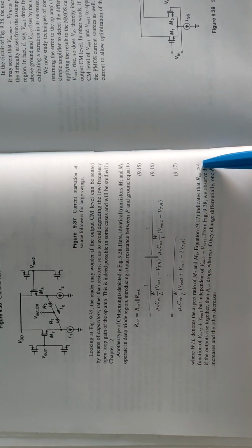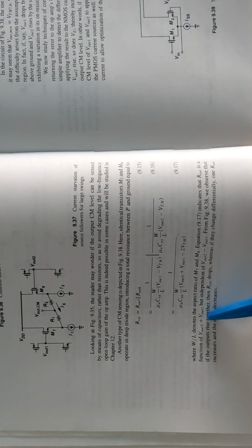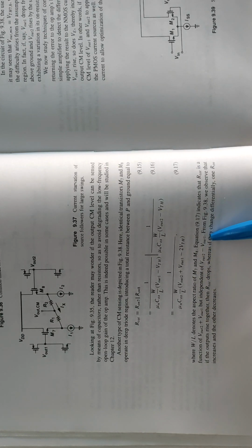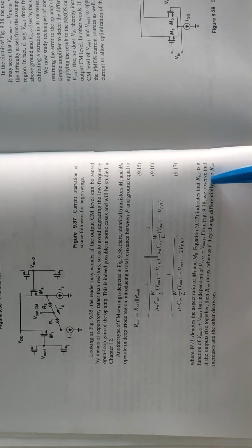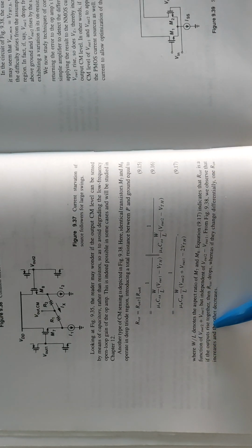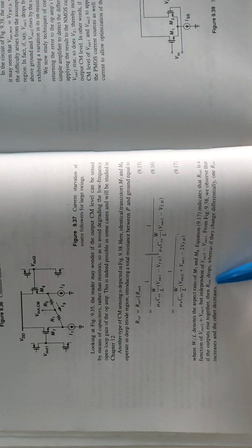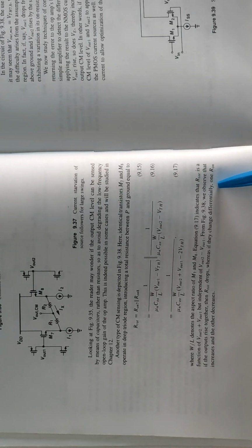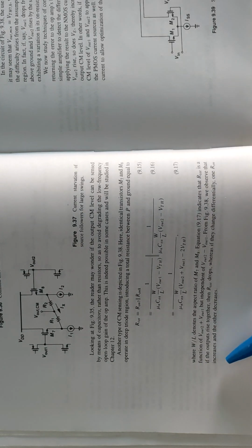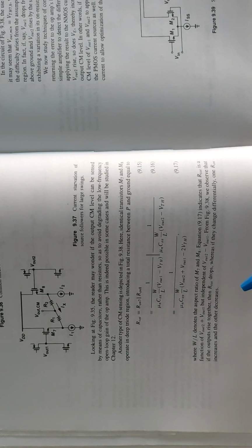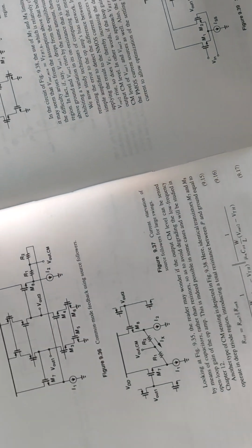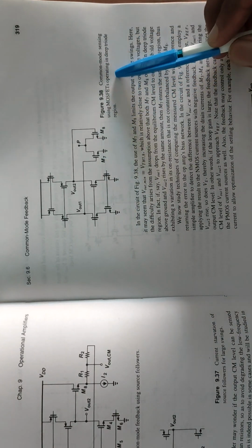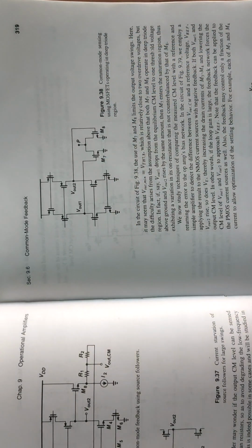The equation indicates that R tot is a function of Vout2 plus Vout1 but independent of Vout2 minus Vout1. From the figure we observe that if the outputs rise together, then R tot drops, whereas if they change differentially, one R on increases and the other decreases. Common mode sensing using MOSFETs operating in deep triode region.